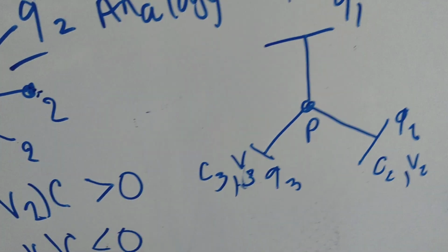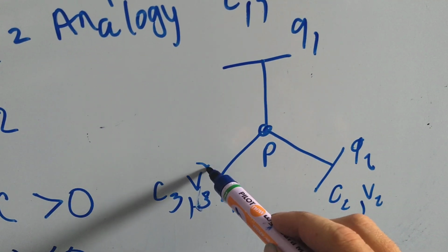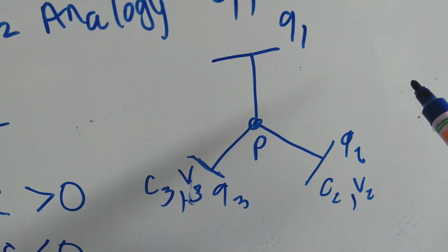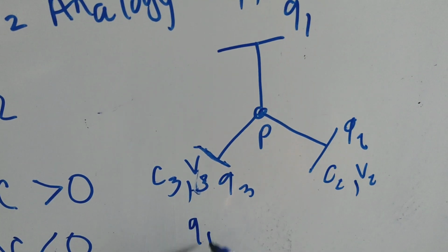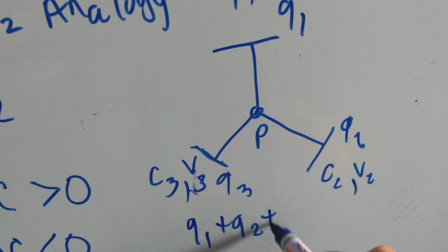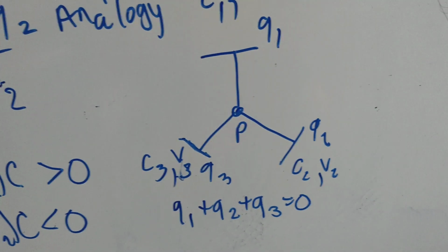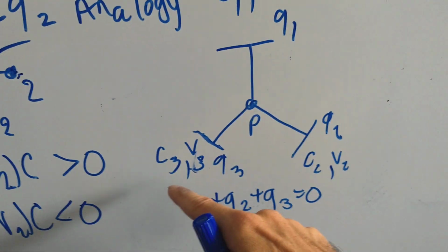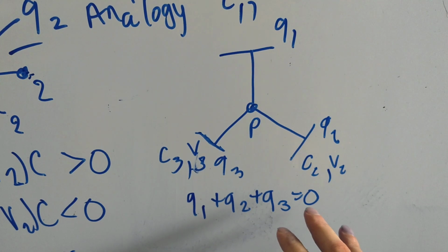Now this is isolated. It's not connected to anything. The fact that they're capacitors is kind of irrelevant to that. The total charge has to be 0 because there's no way for charge to have gotten in or out of there. It was 0 to begin with. After we applied these voltages at the terminals, the charges moved around, but the sum is still 0.